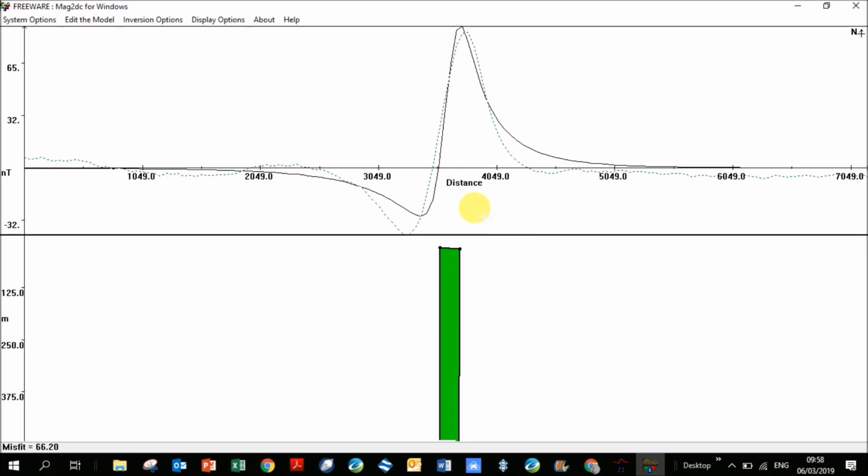You can see then if the surroundings are 100 meters above sea level, and this is 500 meters above sea level, and my flight height was 100 meters above that, then actually this over here is 600 meters where I'm modeling the dike. You've got to take that into account if you've got hectic topography in an area. But if it's relatively flat, it's not a problem.